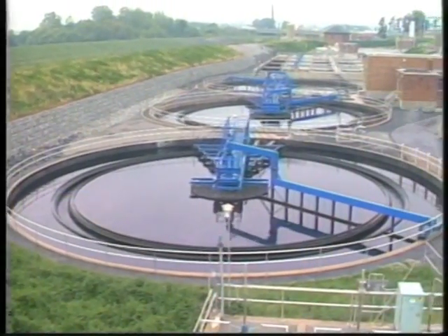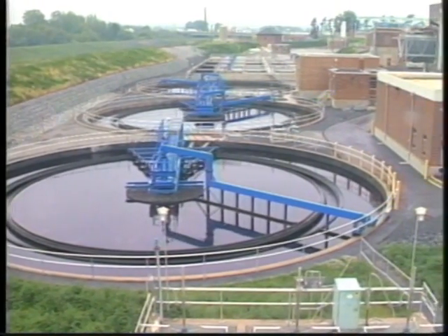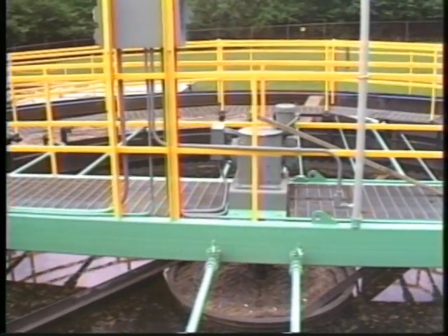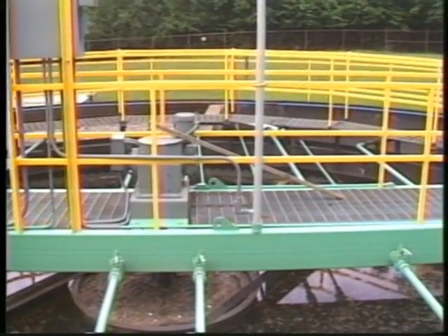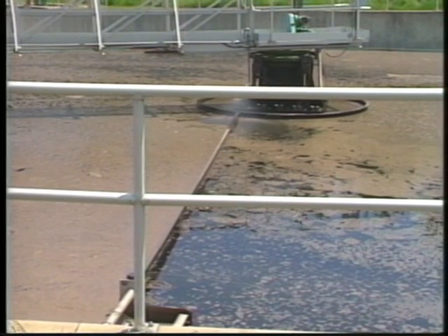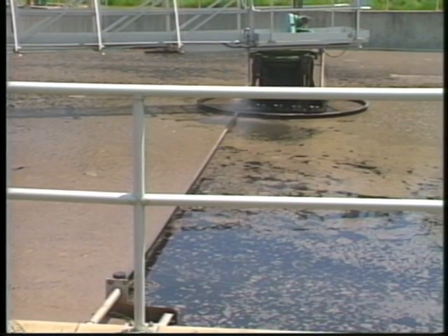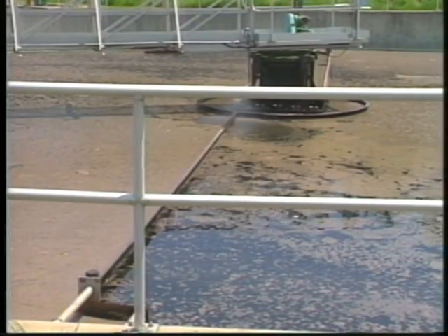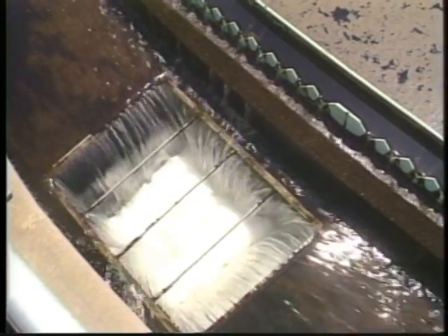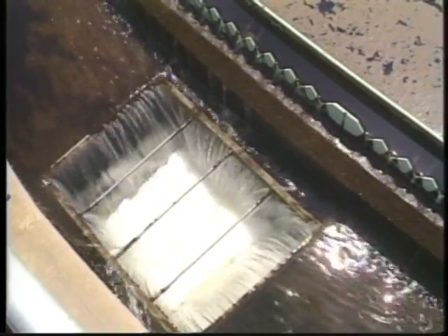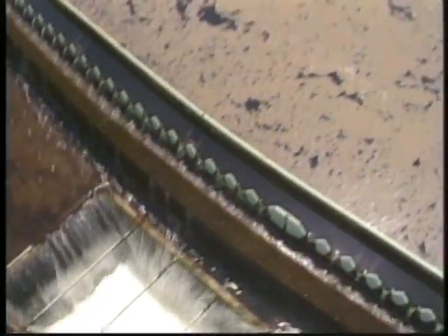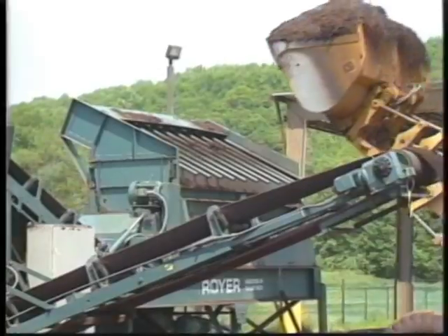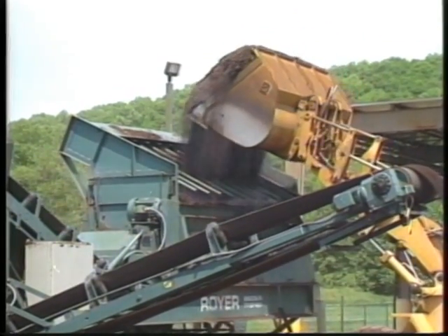Now, let's take a look at the final major component, the clarifier. This unit will usually be constructed of concrete or steel and may be round, square, or rectangular depending on the design of the system. In the clarifier, the hungry activated sludge microorganisms are allowed to settle to the bottom while the clear, treated wastewater is decanted over effluent weirs. The settled microorganisms are then either returned to the aeration tank or disposed of as waste-activated sludge.